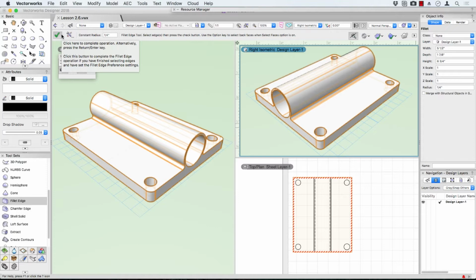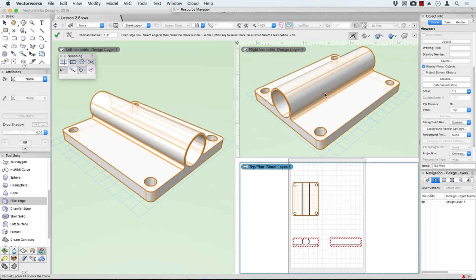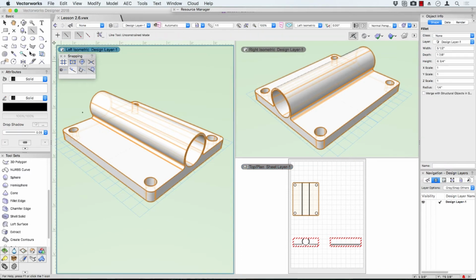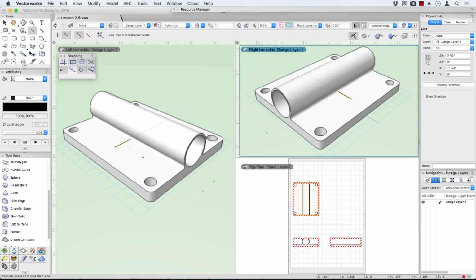So it's a way of selecting other parts of the model that are turned around. So what does that mean over here? Well, if we update our viewport, that's updated. So we've now got the ability to see my entire drawing in this view, plus I can see my model in this view, and I can see part of the model in that view, and I can work in either one. So I could, if I want to, start drawing on this view pane, and I could finish off in that one. It's kind of cool.